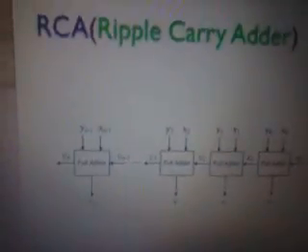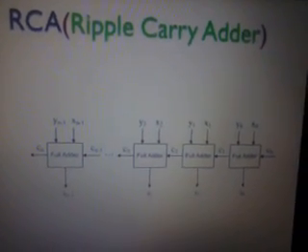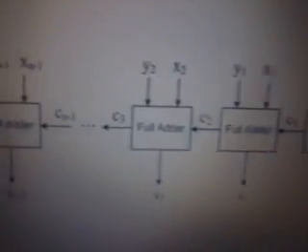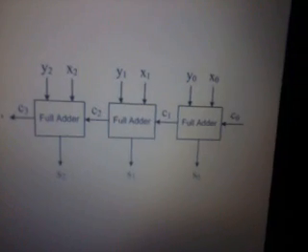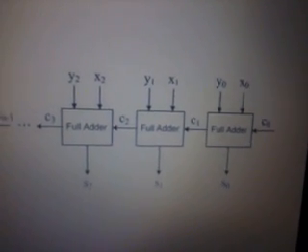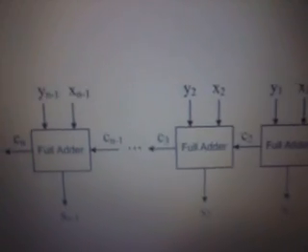This will be the output of our error tolerant adder. We simulated this through the ModelSim software. This is our conventional adder, that is the ripple carry adder. We have full adders, and the carry from one full adder is carried to the next full adder, so it goes like this. Next is the output of the ripple carry adder, which is done through Xilinx.